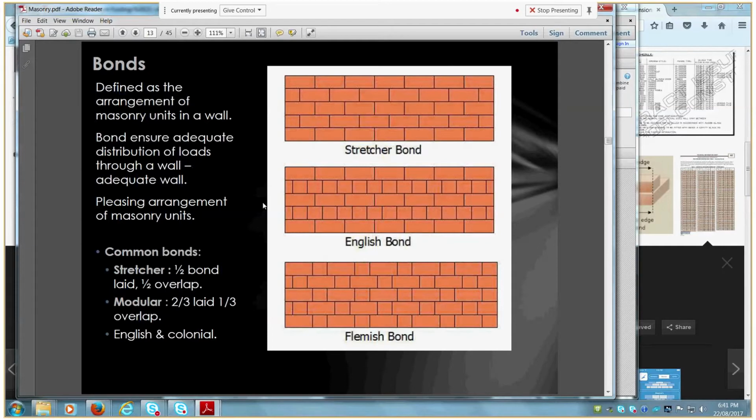What's better insulation-wise, the double brick or the cavity brick? Well, double brick doesn't allow for any insulation, which is an issue with meeting the requirements of the National Construction Code. I can't think of what the R value of bricks are off the top of my head, but it's basically none.